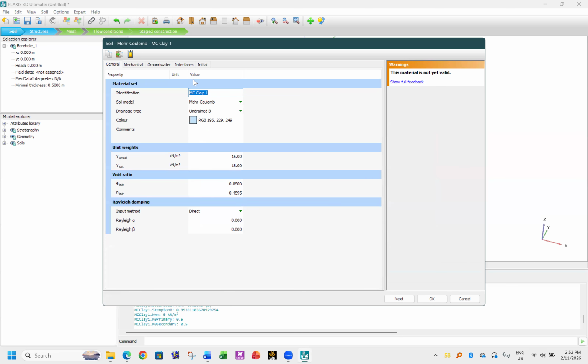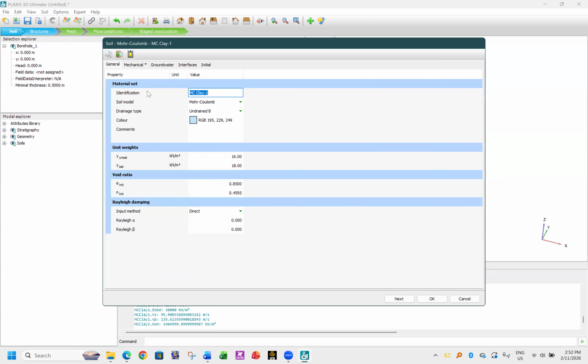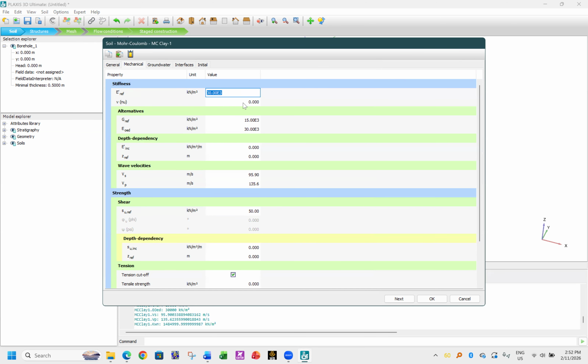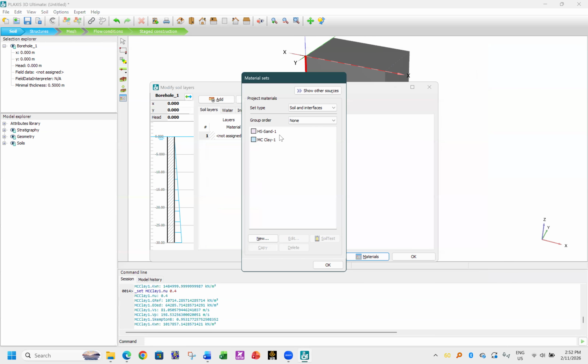Now we can say E is 30,000, and it will come from your material model B. Yes, B is given. Then Poisson's ratio, say for clay soil is 0.4. You have to use your own. You'll come here. So you see these parameters, you don't need anything, only Su or Cu, that is the state is given 50. Okay, it's 50. So your case is for this 60 or 50, whatever you like. So your parameter.